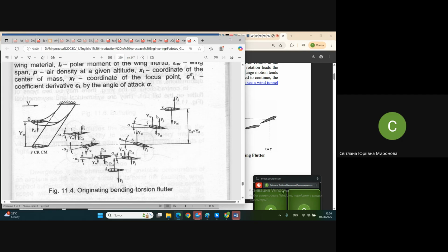If the frequencies ideally coincide, what may happen is a sharp increase of the amplitude of these oscillations, like the energy is joined and multiplied. In terms of technical structure, it may result in sharp and quick destruction of the structure, like we have seen in the movie about flutter. You have witnessed it, it broke the wing immediately in flight.